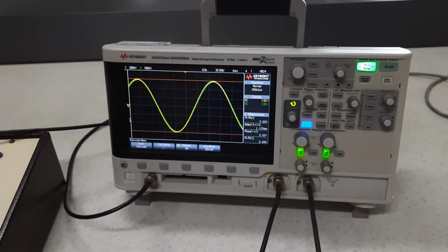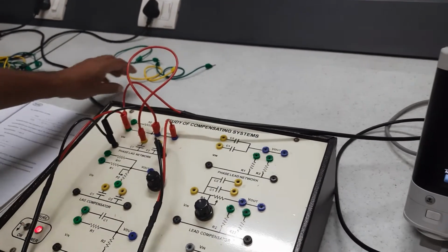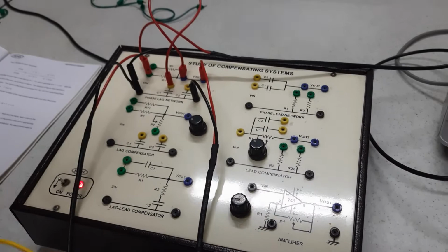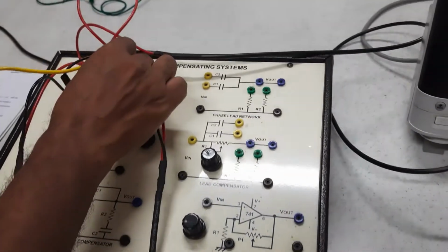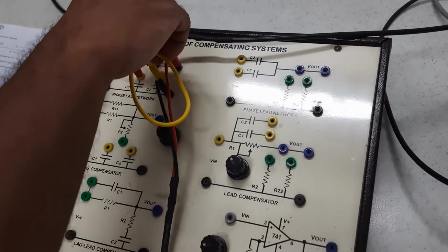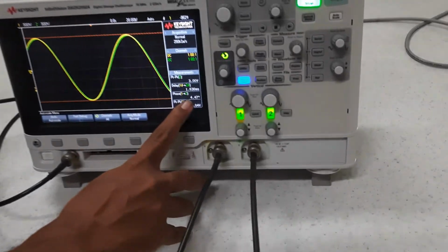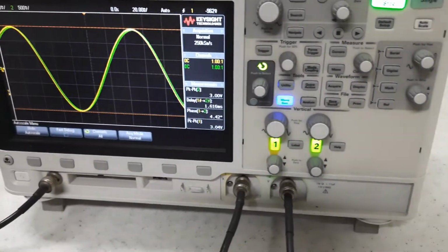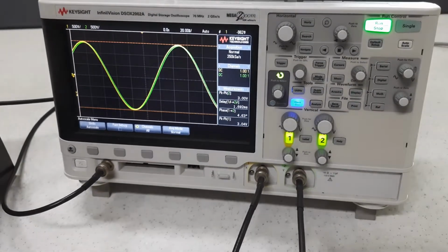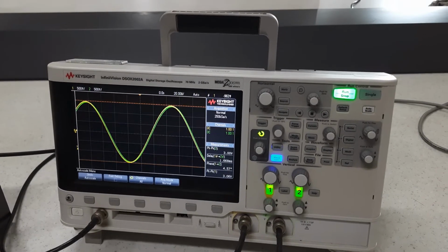Now, why the small phase difference? Because we have used only one capacitor to it. In case I add one more capacitor to it, which means that I am adding more capacitance, right? When I add more capacitance, the phase must increase, right? Now you can see here I have added one more capacitor to our system. Now you see the phase difference, it is close to 4.73 or 4.6 degrees. It is the phase difference between your voltage and current, which means between your input and output.